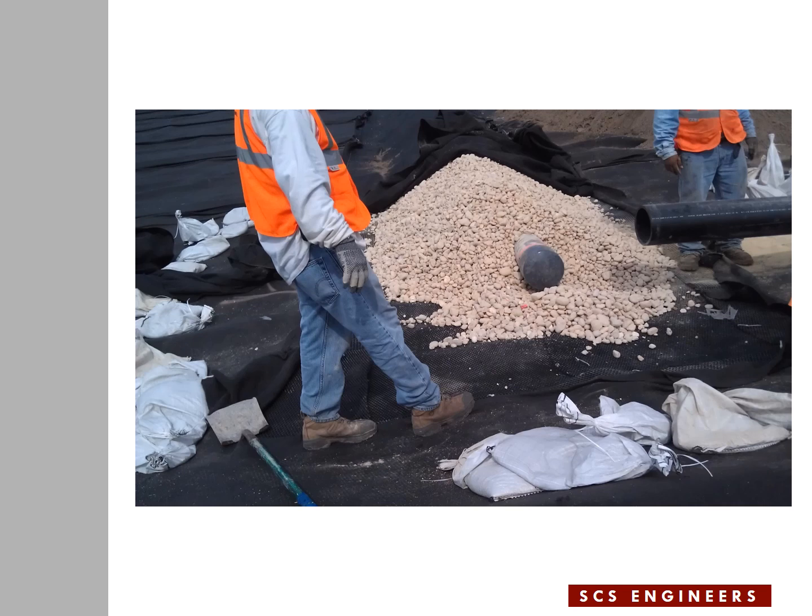Here they have completed the LCS pipe, cut the excess length, put a cap at the high end of the pipe, and the next step is to add gravel around the pipe to embed the pipe, and then the next would be pulling the geotextile over the gravel to protect the gravel. But in the meanwhile, they are going to finish the vacuum line, which you see to the right side, within the gravel space.